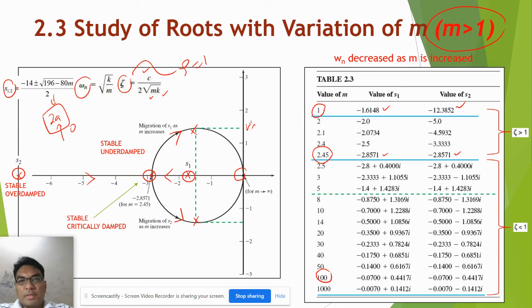The hint is to take the minimum and maximum values first, then the point where the damping ratio is critically damped, giving the three most important plots of the poles. Later you can take 1 or 2 points in between these regions so that you can roughly sketch it.